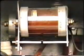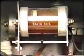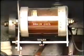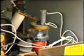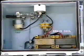Let's get back to our carrier accessories as they are known. The drain coil is made of very light wire and therefore cannot withstand high current or survive high voltages such as lightning transients. This is why the lightning arrestor is installed here. It may be a gas tube protector similar to the type used on telephone circuits or on pilot wire protection. Alternatively, the lightning arrestor could consist of a simple spark gap, such as a spark plug.